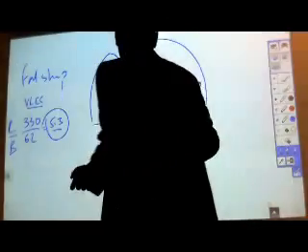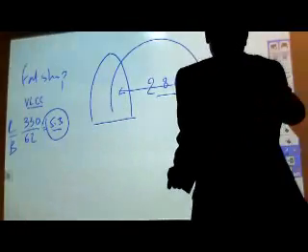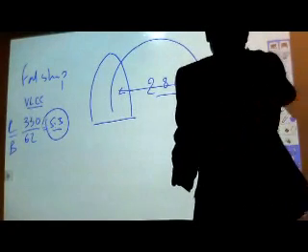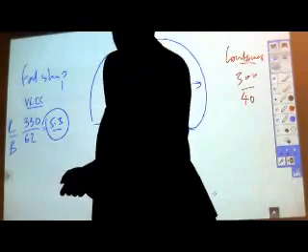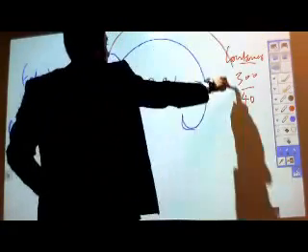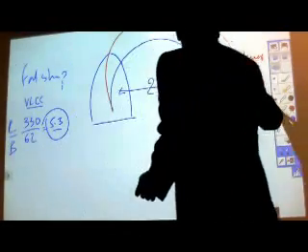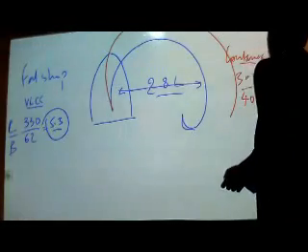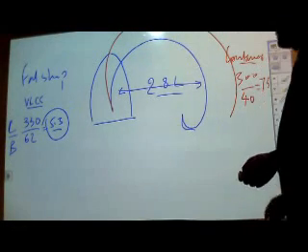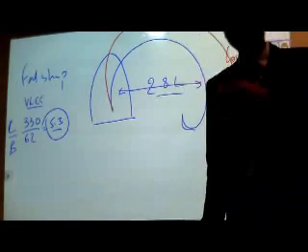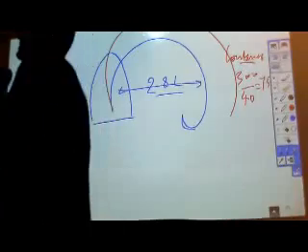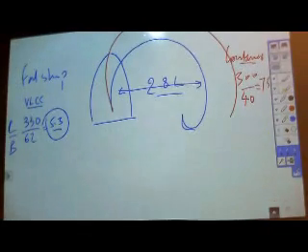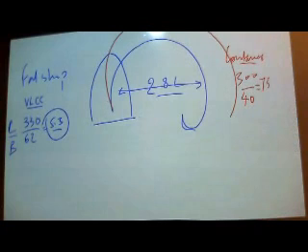For a vessel which is, on the other hand, as I told you, a container vessel, well, this container vessel is going to have a bigger turn. What did we say? This was 7.1. But this vessel is going to be very directionally stable. You will not need to apply continuous and regular steering, the rudder again and again, to control this vessel.